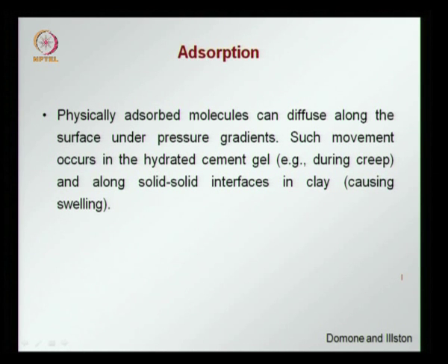We also know that physically adsorbed molecules can diffuse along the surface under pressure gradients. That is, if you have water adsorbed on a surface and pressure is applied that drives the water, these adsorbed molecules, instead of being released into the atmosphere, will travel across the surface. Such movement occurs during creep in hydrated cement gel, the calcium silicate hydrate gel, where water moves during creep, and also in clays, where we have water moving along the interfaces between the clay platelets. This was discussed in a previous lecture, and this causes swelling. Water moving into the interface between the clay platelets gives rise to swelling in some types of clay.